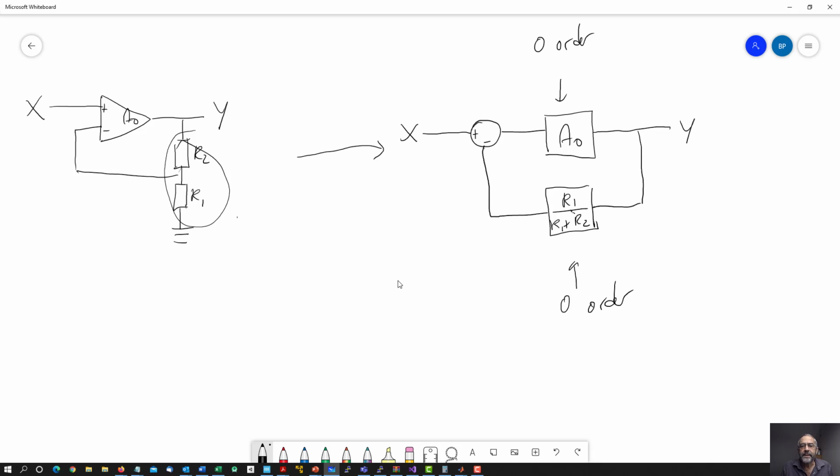But what we have to do is add arrows to show the direction of things. What we have to do is calculate the transfer function of this whole system. That's our goal. Well, that's easy. We know the loop reduction rule. We just saw that. We have already determined our H1. H1 is this, and H2 is this.